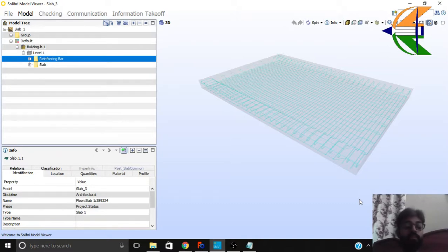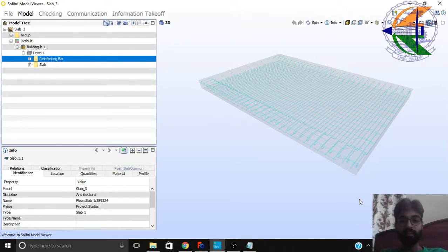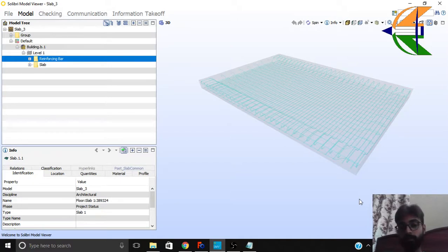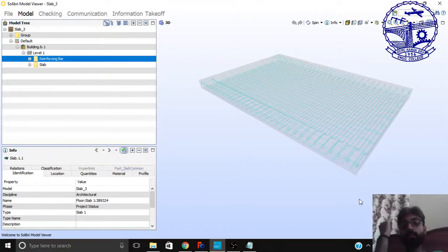If we really want to go for open BIM, it's not just about reading and exporting the IFC. The information should also be there. If a commercial BIM software is exporting its information through its own native format, then it should be capable of importing and exporting the details to IFC as well. I don't know how they are getting the buildingSMART certification if they are not relying on these standards.